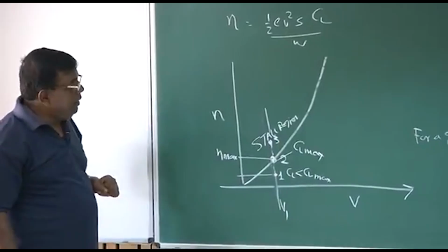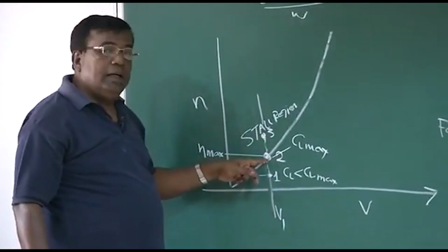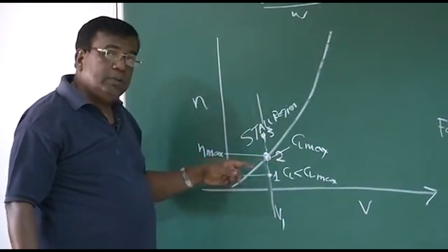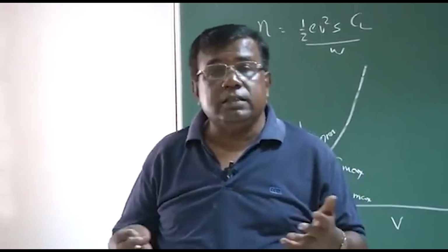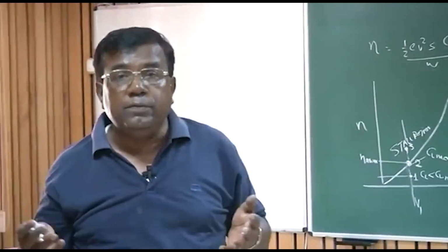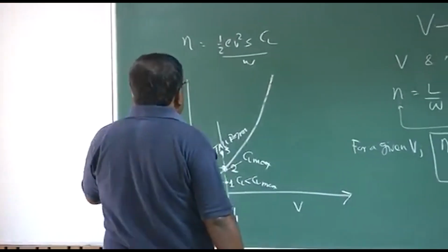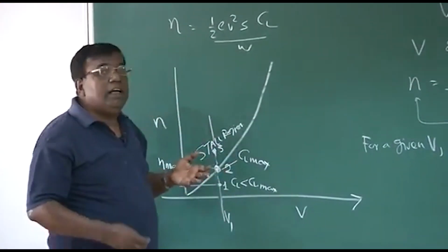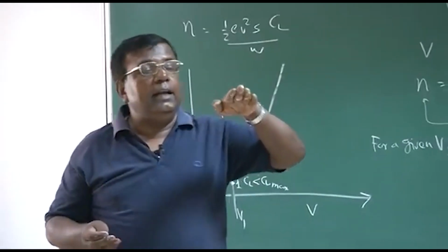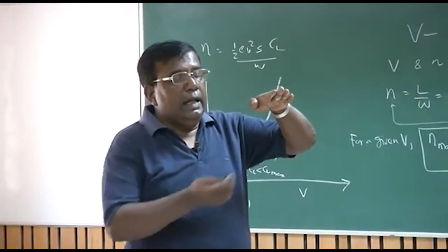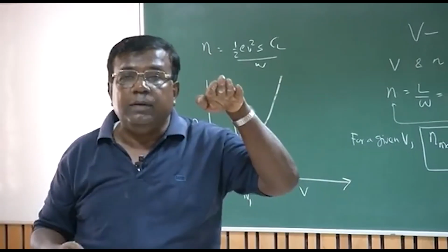Please understand another very practical thing. Suppose a pilot is flying the airplane somewhere here on this VN diagram. But this VN diagram is not giving any description about the wind gust available in the atmosphere. Right? So it is important when you are drawing a VN diagram, I should also superimpose the gust profile. For example, suppose I am going like this at an angle of attack, say 10 degrees, and suddenly there is an upward gust. So that will change the angle of attack of the airplane.